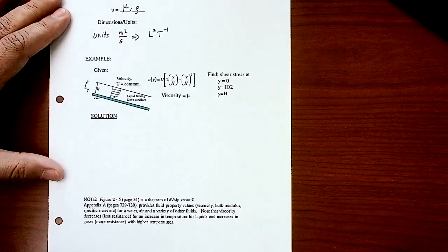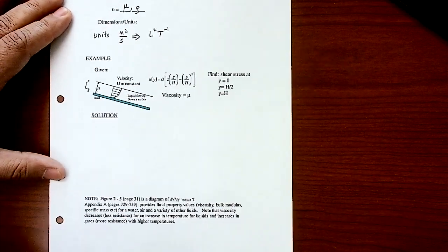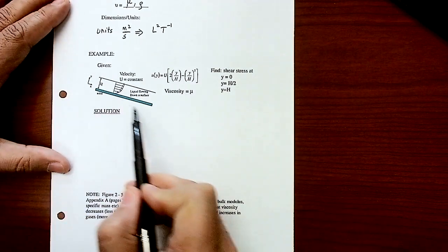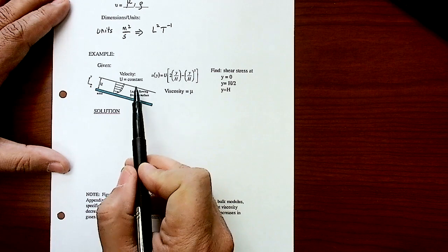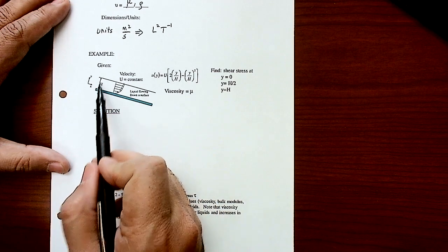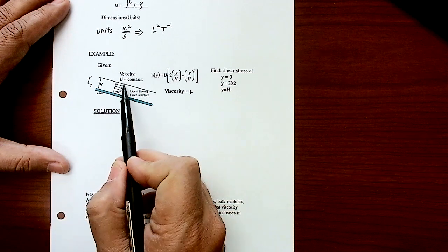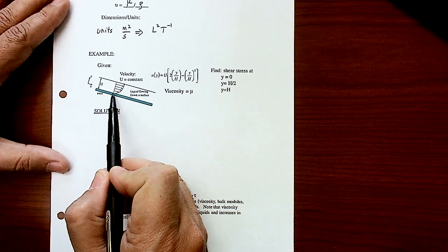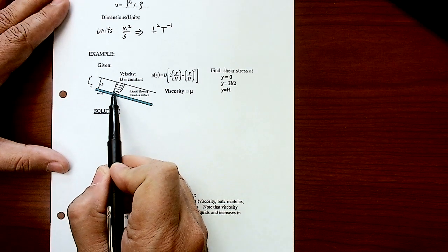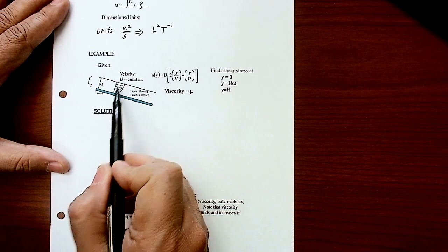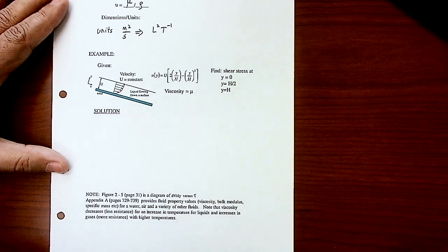This is an example here, and this will be close to some of the homework assignments. So this is a tilted plate. There's a fluid moving above that plate. The thickness of the fluid layer is H, okay? And this is how the velocity distribution looks. So the velocity with no slip condition shows zero velocity for the first layer. You go a little bit up, it's increasing velocity. You go a little bit up, it's increasing velocity, until almost the velocity is not going to change too much here. So this is what we call the velocity distribution.